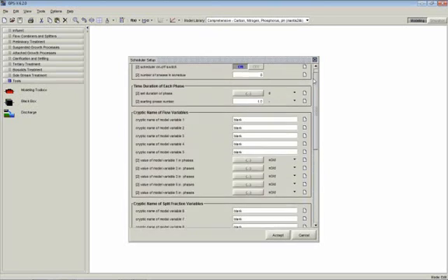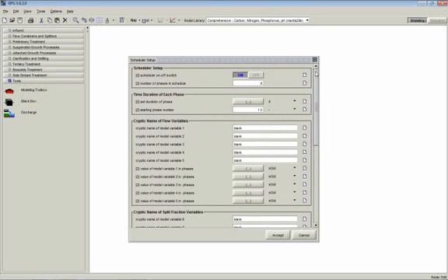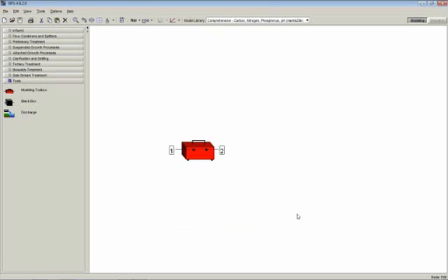And that will allow you to do things like, for example, if you have a batch system and you're feeding one tank for a period of time and then feeding another tank and then another tank, if you have SBRs, for example, this is very handy to be able to schedule those phases, have a number of pumps turn on and off, and flow splits all change together at the same time. So this is very handy, very open-ended. You can do a lot of interesting things with it.